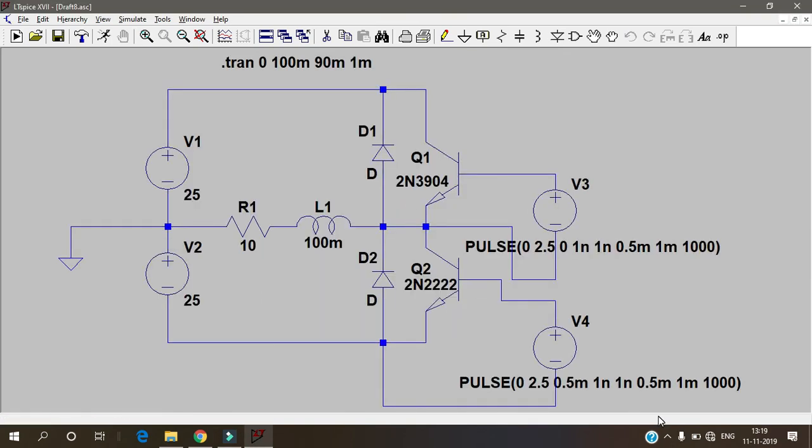That's it. A very important thing that you have to notice is this ground. Okay, this doesn't have a common ground, so we must give this negative terminal to this, because this is the emitter terminal and this is the base terminal, and this should be connected like this. This is why isolation is usually needed when we supply base voltages.